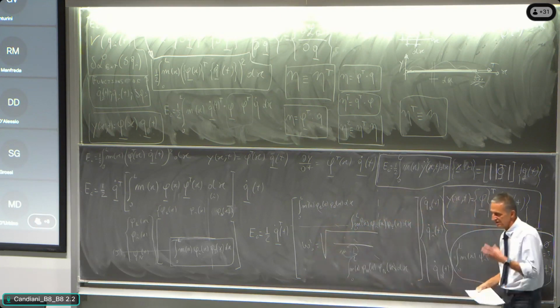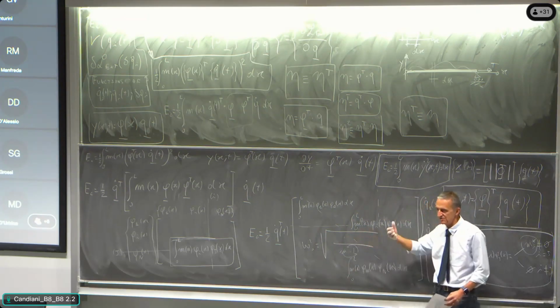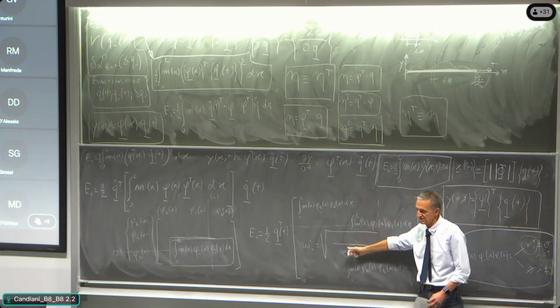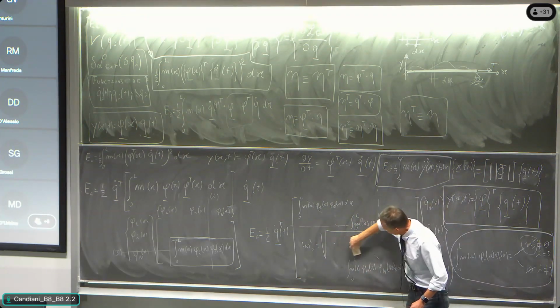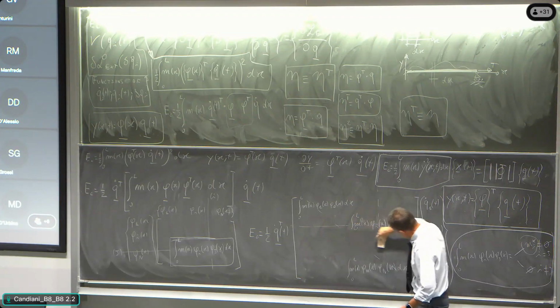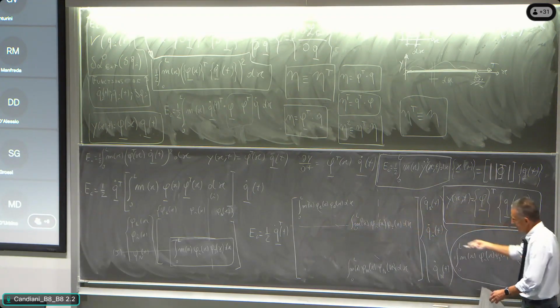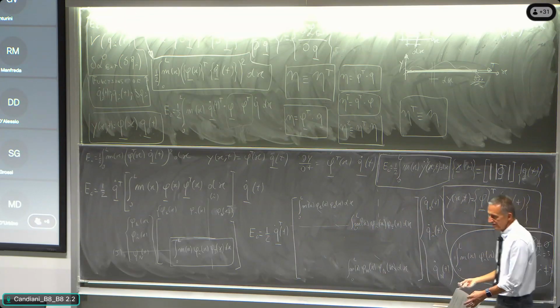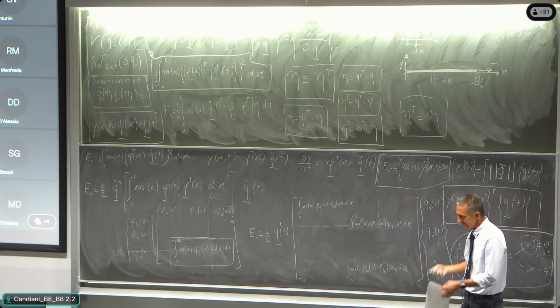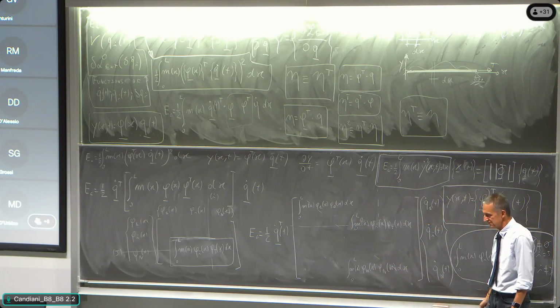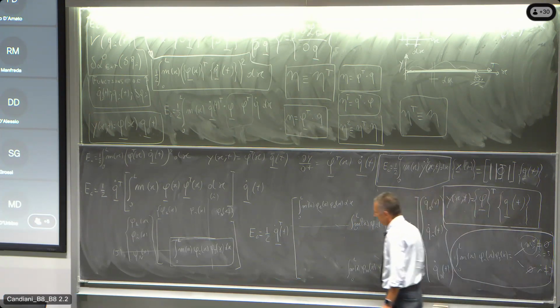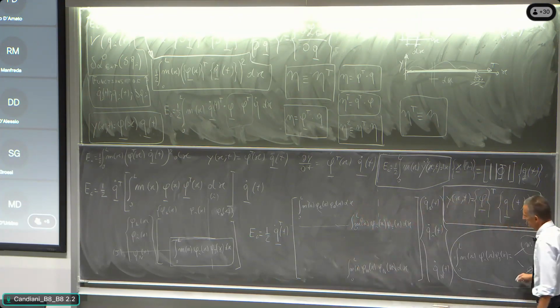Yes, we understood that what is over the fraction line is the modal stiffness, and below the fraction line is the modal mass. But doing the dynamics of the structure, we can calculate exactly what the modal mass is: the weighted distribution of mass integrated through the modal shapes. All right? And the orthogonality is that all of that is diagonal.